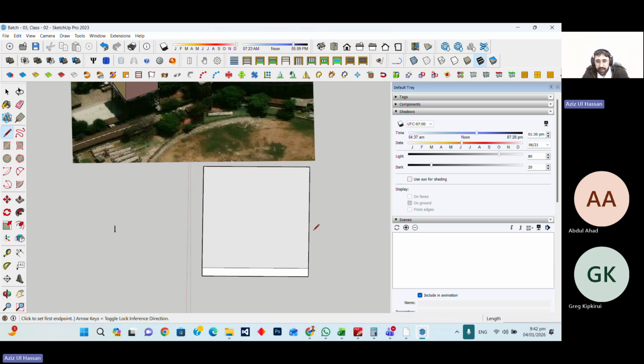Which side you have to give the tilt on: we have to give the tilt angle along that length area, so that it is in a tilted form. Here, parallel to the 200 side, you should give the tilt angles. Whichever side you want to give the tilt angle, you just mark one center line. Okay, now what should you do? Use the move command.